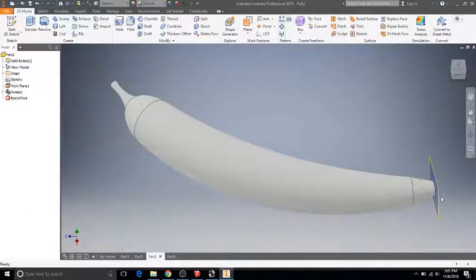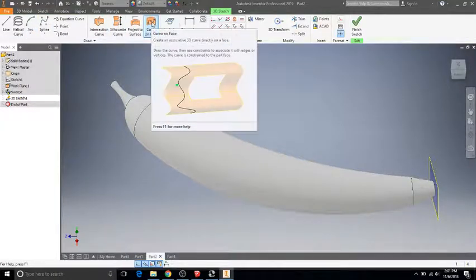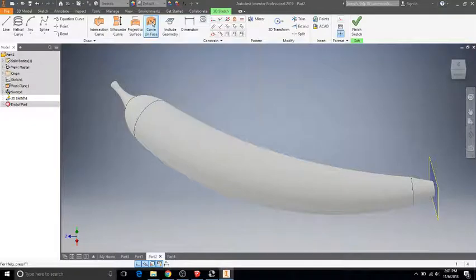Throughout this class we've been drawing with 2-dimensional sketches. There are other options for drawing in this program. If you see this little drop down arrow, you can actually create things like 3D sketches, and this might be something you'd be playing around with in our project. Okay, this one's really easy to use, pretty intuitive, just like the spline tool, except I'm going to be drawing